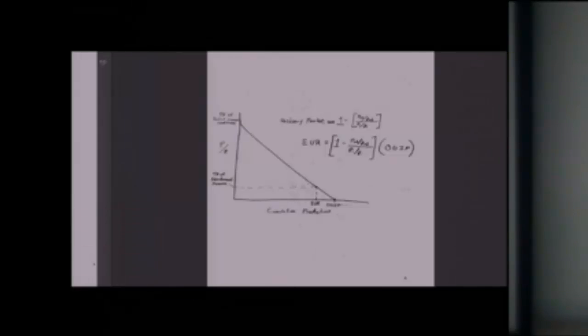So it's one thing to know how much gas is in place, and of course what we normally do is produce the well for a while, measure the pressure, and calculate a P over Z. And then calculate another P over Z, and then make some kind of extrapolation of that line as the way it's normally done.